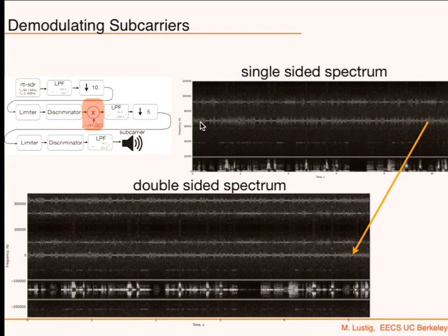So I'm going to display now a two-sided spectrum in which this shows up in the middle at 0. It shifts the whole spectrum. Really, it's a two-sided thing, but it was just a mirror of it. When I do demodulation by e to the 2 pi j, whatever the frequency is, it kind of circularly shifts it.